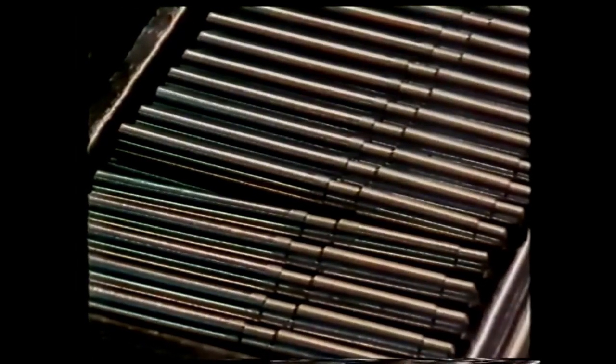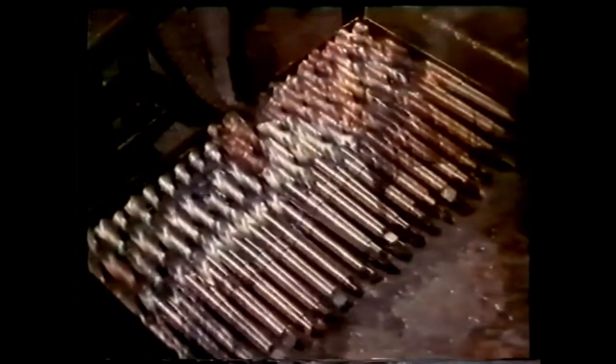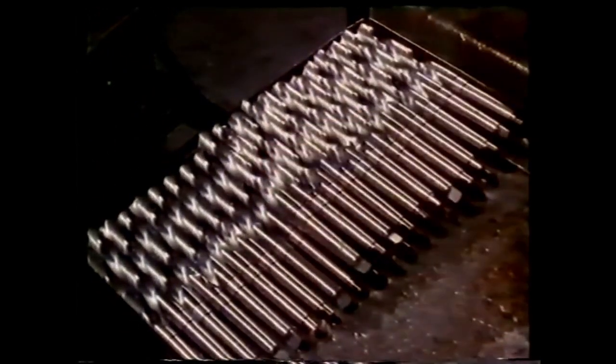On larger twist drills, the fluting is milled onto the high-speed steel before heat treatment, which of course would make the metal harder and more difficult to machine. After milling, the drills are heat treated in several stages. An automated carousel ensures that the drills remain in the liquid salt baths for the right period of time. Smaller twist drills are made entirely from high-speed steel, and because of their size, are heat-treated before the fluting is ground out of the metal.